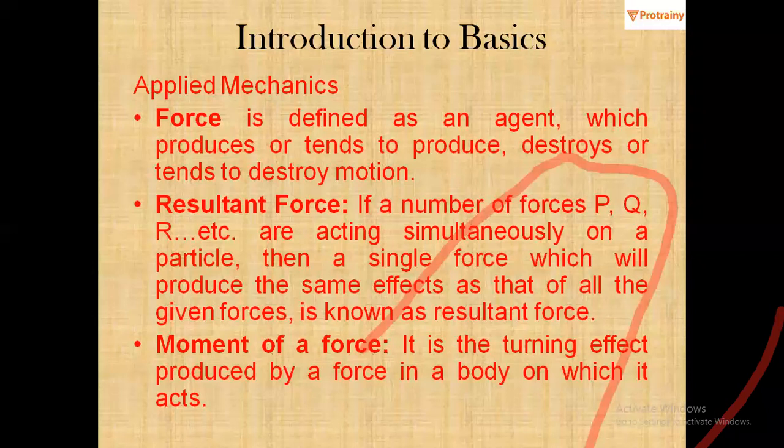Then comes moment of a force. So what is moment of a force? जो beam theory है, या when we will be talking about flexural members, the members which actually bend, that is all about moment. So what exactly moment of force is? It is the turning effect produced by a force in a body on which it acts.